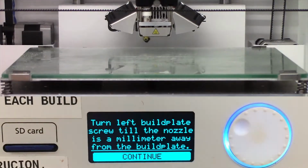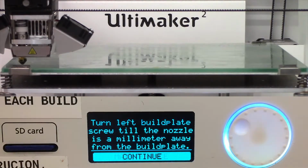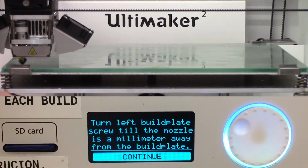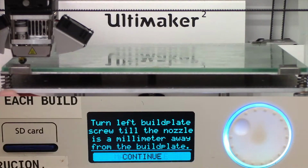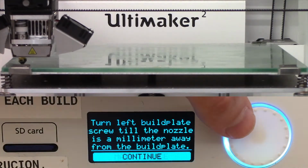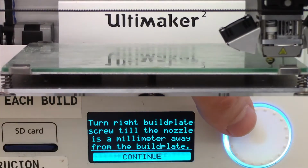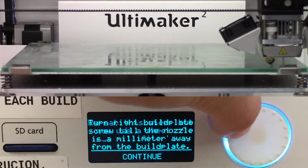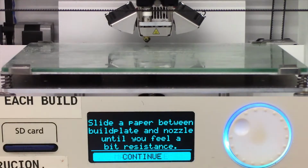Then we'll go ahead and depress the button to have the nozzle come to the front left area of the build tray. Now the goal is the same, to bring the tray about 1 millimeter away from the nozzle tip, except we won't be using the dial as we did before. We'll be using these set screws. It's important to note that in order to lower the tray, we'll tighten the screw, i.e. twist it clockwise, and to raise the tray, we will loosen the screw, twisting it counterclockwise. Now the front right of the tray also looks good, so we'll depress the button again and get ready for the next step of initializing the print.